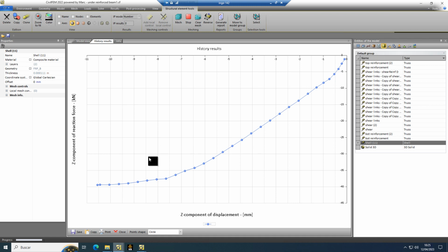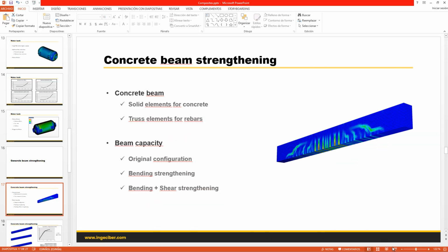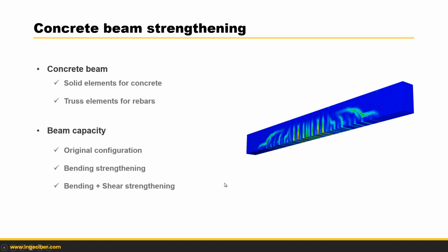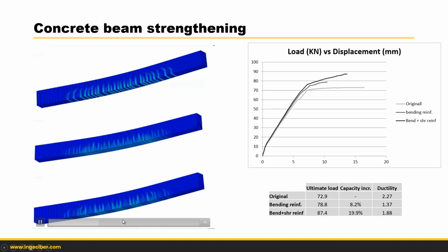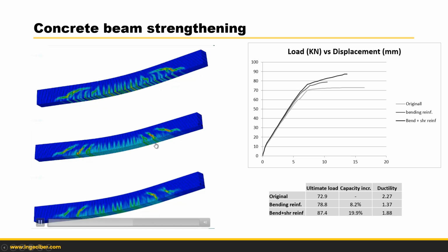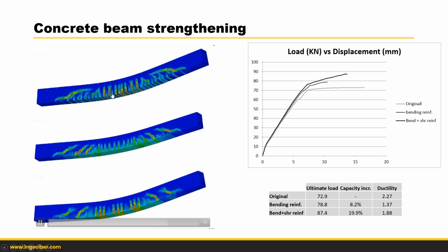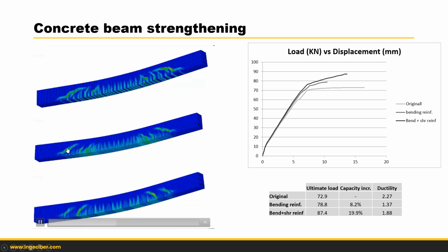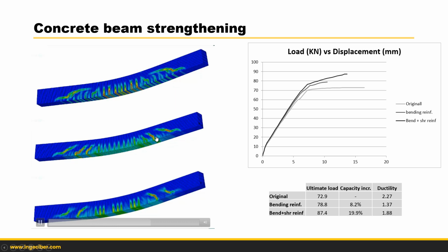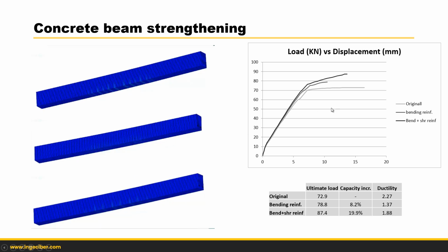So well, going again to the PowerPoint, we can see here in PowerPoint 3 different videos with the different 3 configurations where different cracks are happening. Here bending cracking is the main failure. The second one is the failure is due to the shear crack and the shear yielding on reinforcement, and the last one is due again to bending or bending plus shear at the same time.